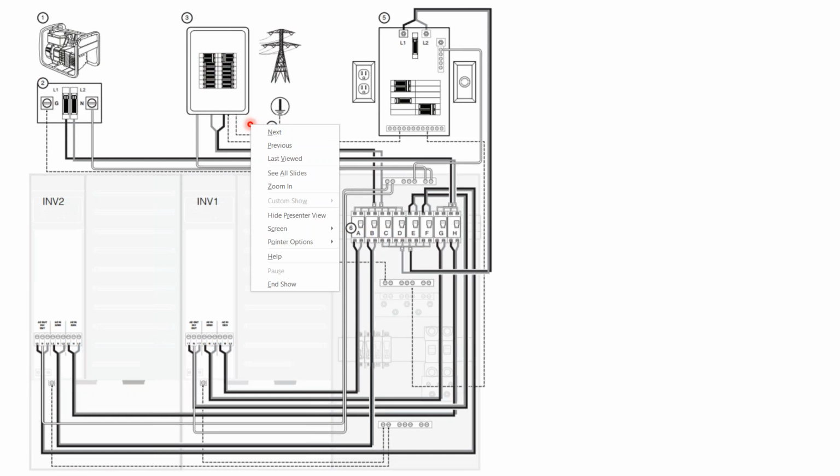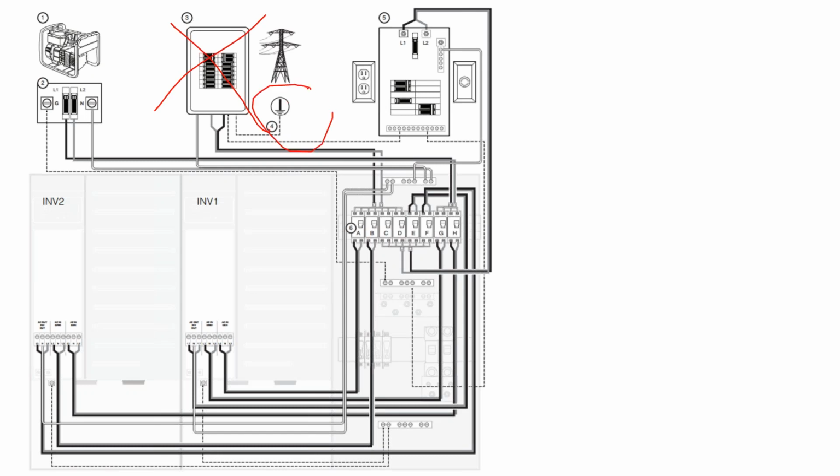So what we got into on our point is, when we eliminate this grid connection, the question is, well, we've also eliminated where the neutral is being bonded to ground. Here we have our neutral bar, and so the field question is, do we bond neutral to ground at that point? There's only one neutral to ground in this kind of system.